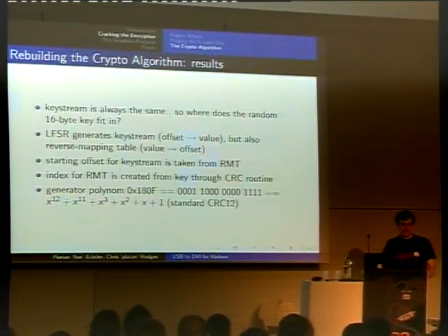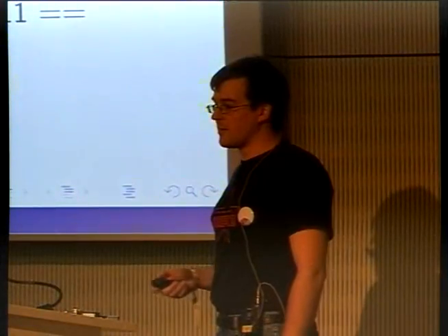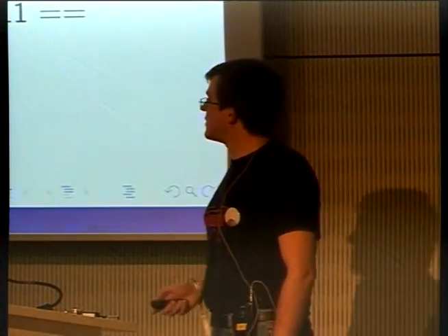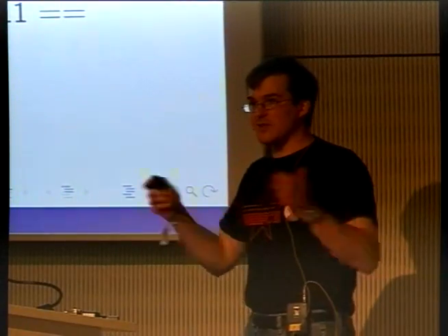The CRC of this key is just fed into the LFSR on the device, which then starts generating the same key stream as in the driver. So this is in fact a standard CRC12, and it looks like the device doesn't even generate the entire key stream in memory, but just always pulls a single value from the shift register and then advances it by one.